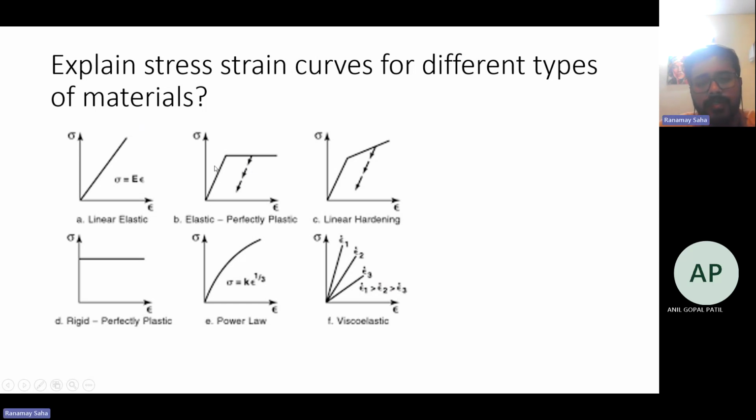Suppose the material is deformed beyond that elastic point, and there you want to pull back the material, remove the load, and get the material back to its original point. Does that work? It has already reached its plastic region of deformation, so it doesn't come back to its original shape and size, right? So whatever you try, there will always be a permanent deformation that remains.